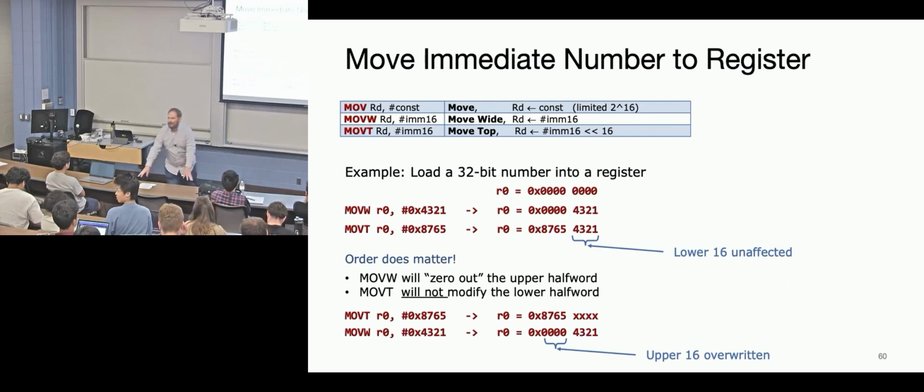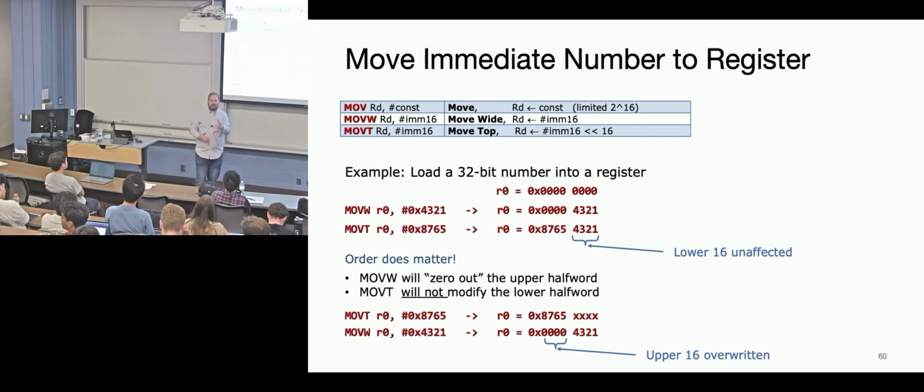So you're saying we can move a 16-bit immediate, but in the encodings we looked at, there were only 11 or 12 bits dedicated to it? Correct. We did not look at all the move immediates that are possible. There are lots. So we could just look in the instruction set, it'll tell us what's available. What's the difference between an immediate and a constant? I don't think there's any difference.